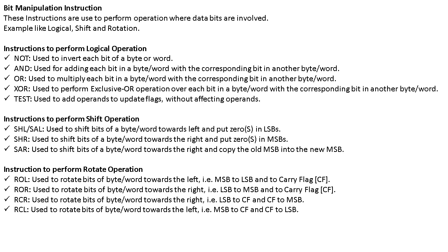NOT, used to invert each bit of a byte or word. AND, used for ANDing each bit in a byte or word with the corresponding bit in another byte or word. OR, used to OR each bit in a byte or word with the corresponding bit in another byte or word. XOR, used to perform the exclusive OR operation over each bit in a byte or word with the corresponding bit in another byte or word.